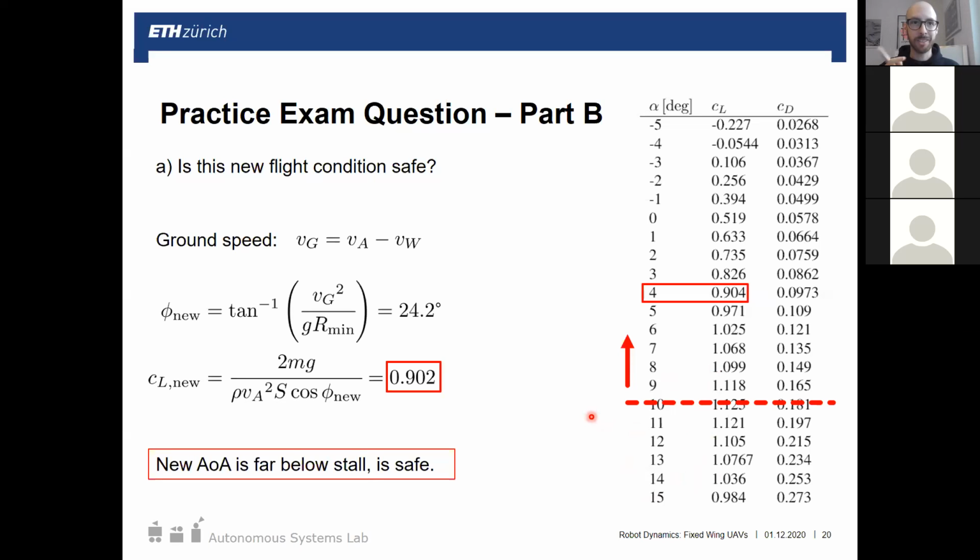Maybe, I haven't seen the slides yet, so maybe David and Mike, or Sebastian, will show you what this post-stall curve looks like, all the way to like 90 degrees angle of attack, for example. For regular fixed wing planes in cruise flight, we definitely don't want to go past the stall point. But if you were to go all the way past the stall point, so far beyond 15 degrees, for example, at some point the drop off kind of rounds out, and there's a condition called deep stall.